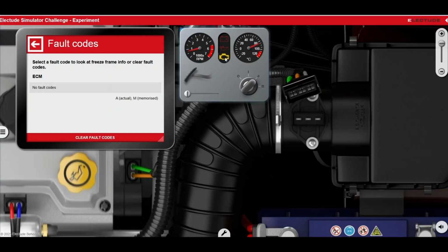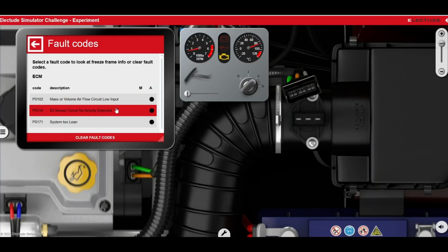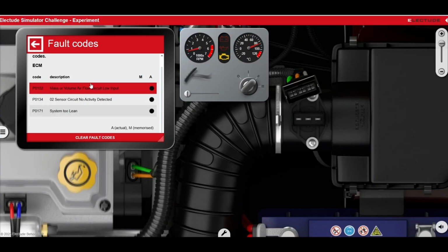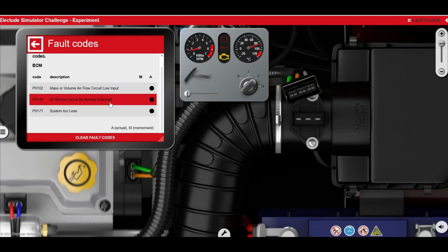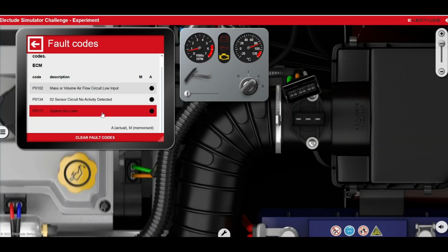That's why a car with a faulty mass airflow circuit will consume a lot of fuel. It will continue running, but will consume a lot of fuel. You can see the check engine light is on over there. Let's go back, try to read the code. You can see a code for mass airflow on top, accompanied by one for the oxygen sensor and system tooling. Let's restore that.